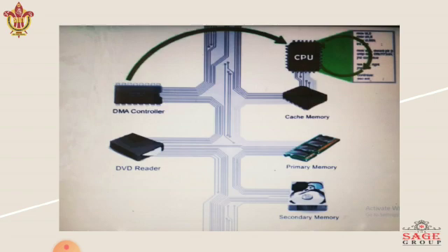Such an interrupt indicates completion of the data transfer, and hence the CPU takes back control of the data bus, which completes the direct memory access.